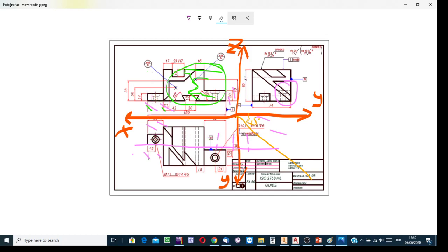You see here we found a rectangle on the front view. Following the transfer lines, another rectangle on the top view, and these 2 rectangles correspond to one more rectangle on the third view, on the left side view. This means that the feature is a rectangular prism.